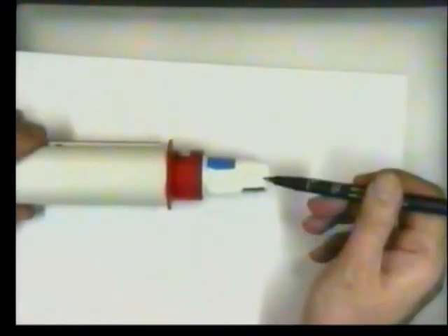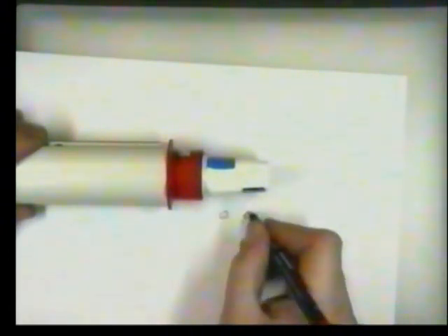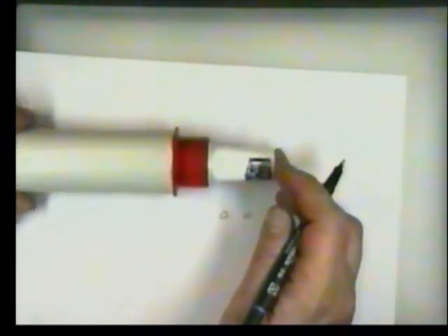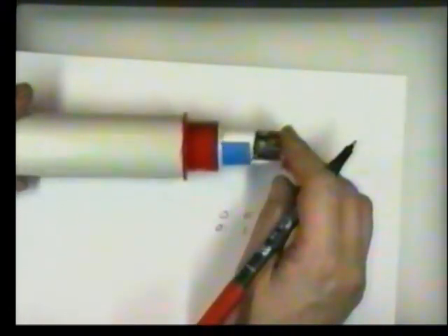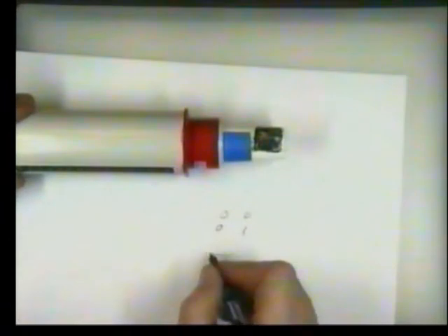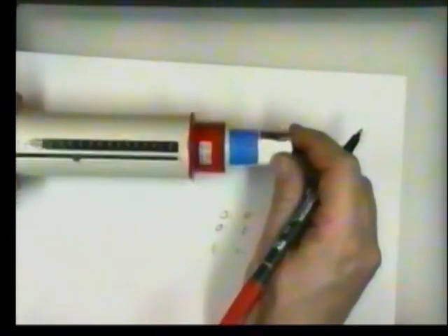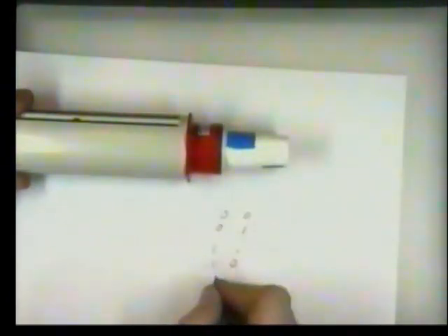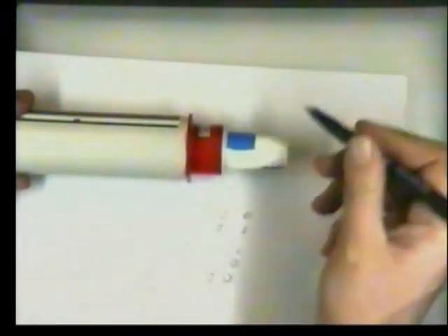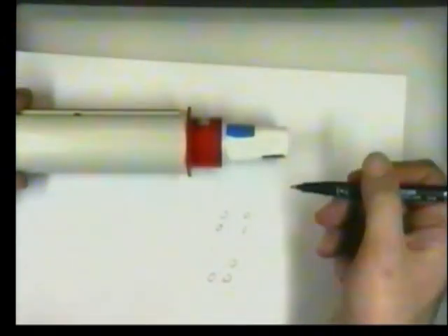Start from rest, and we're just going to look along the center line here, and we have 0, 0. We rotate a little bit, and it goes to 0, 1. Rotate a bit more till we get another change of state. Now we have 1, 1. Keep rotating in that direction, we get 1, 0, and now we return back to the start. That was one rotation.